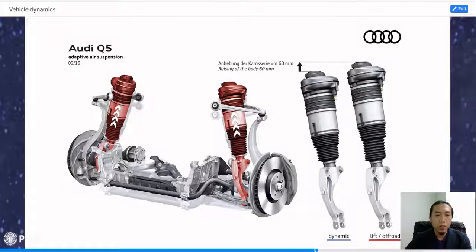Active suspension also controls the vertical movement of the vehicle relative to the vehicle body, implementing an onboard system that senses the forces applied to the wheel, and the system will then adjust the various mechanical connections to maintain the chassis level of the vehicle body.